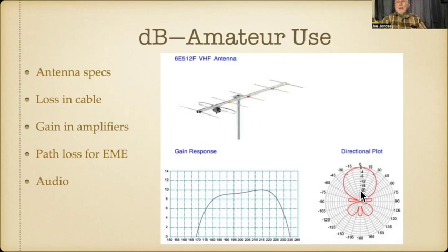So you get much more signal from the front of the antenna than you do from the back. And you see these deep notches here? If you had somebody who was really interfering with you, if you turned your antenna just so that he was coming off this notch here, even if somebody were coming from this direction here, you could tune that guy out and actually be able to receive this guy here, much improving your signal.